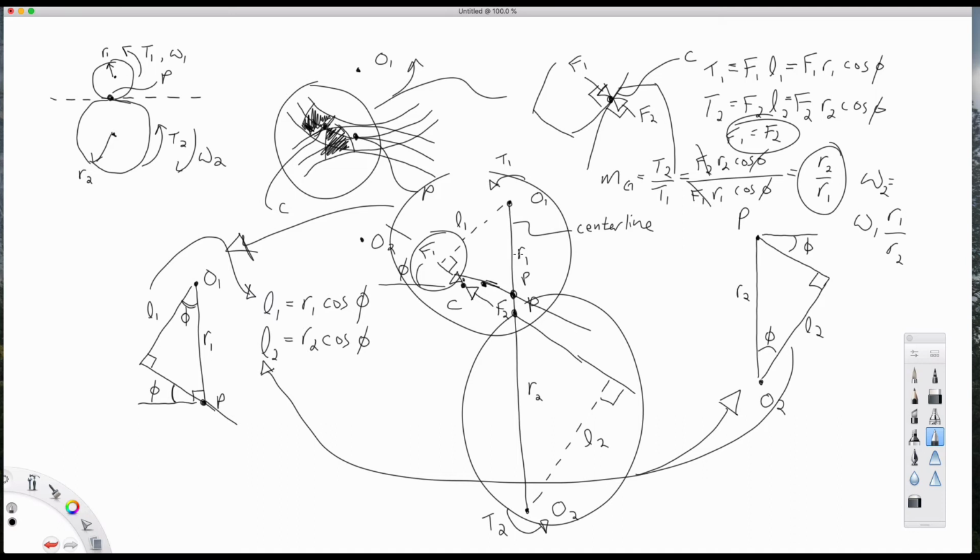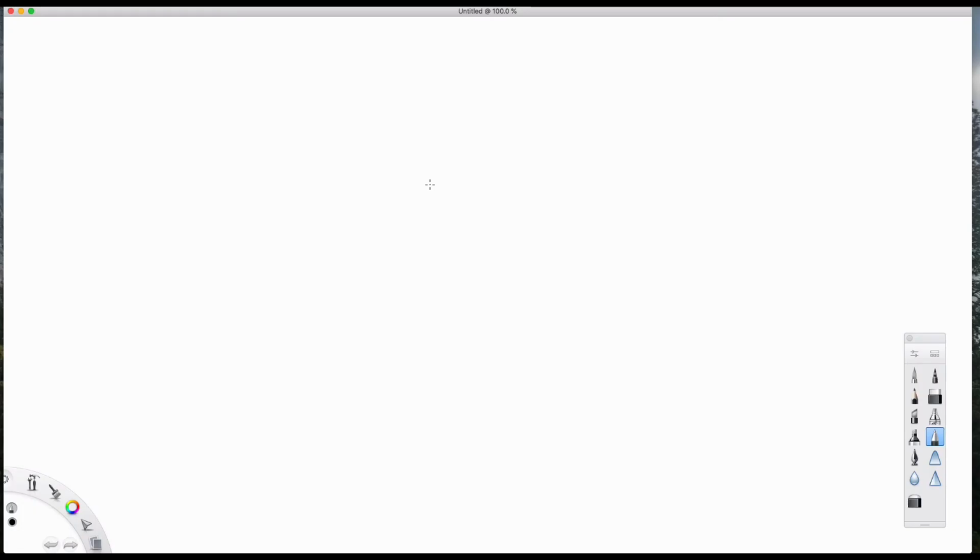So here we're trying to derive how we get a tooth shape such that we keep a constant pressure angle, this line of action, so that the pitch point doesn't move around, so that the pitch radii R1 and R2 stay the same, and then we get this constant speed ratio. Let's have another quick look at this potential for change of location of the pitch point and change of length of the pitch radii and the effect on the speed ratio.